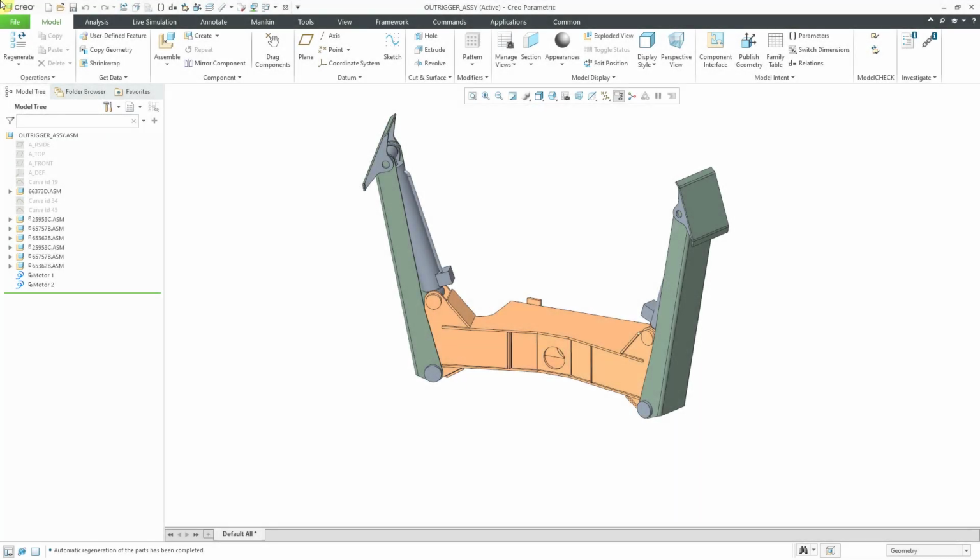In Creo Parametric, you can calculate the degrees of freedom and redundancies for a mechanism. First though, let me show you how my mechanism works. If you take a look in the model tree, I have a whole bunch of components with a dot inside of a box. That means that those components have a mechanism connection instead of traditional constraints like coincident, normal, parallel, distance, and so forth. You can also see that I have a couple motors as features at the assembly level.